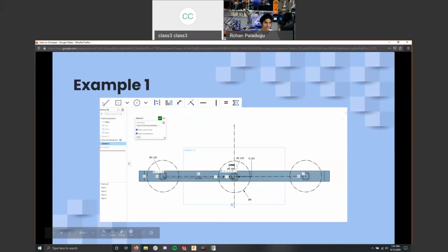So up here, I've included all the sketch entities and relations that I used. So let's just figure out where I used where. I used the line constraint here to create my chain paths. That's what these are here, and I use these to help find my center to center distance. Just a quick rundown of what that is.